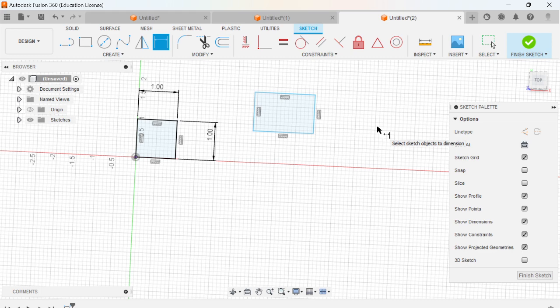Black lines mean they're fully dimensioned, right? All of these points, lines are made up of tons of points, all the endpoints. Everything on this path of the square is dimensioned. It has one set place in space. It's given a place from the X and the Y, right? If I were to click on any of this, I can't move it because it's fully dimensioned.